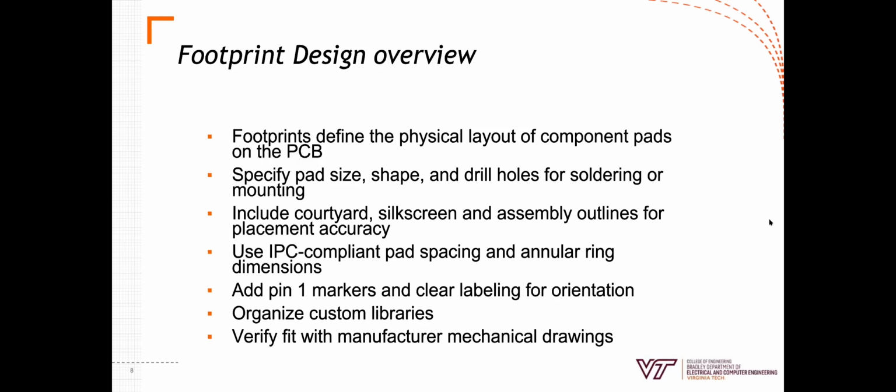These include courtyards, and a courtyard is basically a keep-out zone around the IC that doesn't let you place parts within other parts. And then utilize silkscreens to make sure that you have good references, so you know, like, U1 is associated to a 555 timer, or this resistor is R1, this resistor is R2.